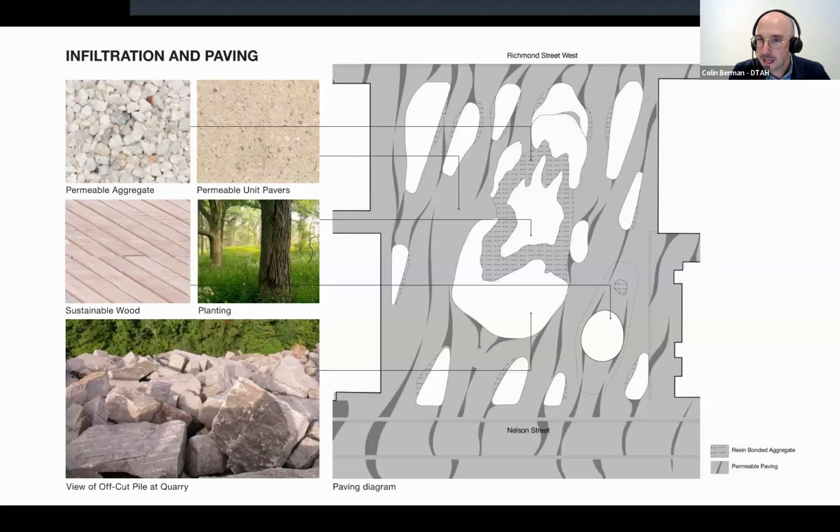We worked hard to peel back the hermetic surface of a typical plaza by integrating permeable paving into the site, achieving 87% permeable surfaces. The grading across the site is also important. It offers flood protection, not only here, but also in surrounding areas. Acting like a natural sponge, the site captures rainwater and helps recharge the aquifer. It will retain the first 20 millimeters of rainfall from storms, surpassing the City of Toronto's standard, which only requires 5 millimeters of retention.